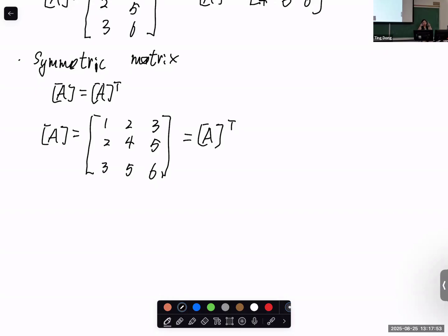For this stress matrix in the global XYZ coordinates, we need to find the principal stresses, which means that for this 3 by 3 matrix, we need to calculate the eigenvalues. All shear stress becomes 0, only the normal stress stays, and we compare the maximum normal stress, or maximum principal stress, with the allowable strength of the material, and we decide whether it will fail or not, right?